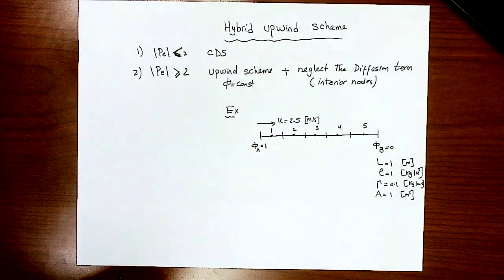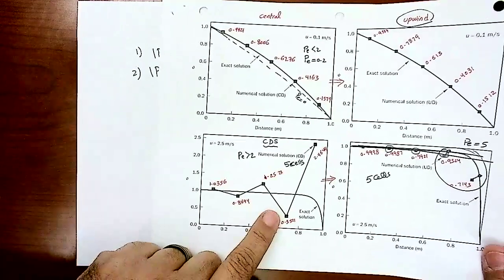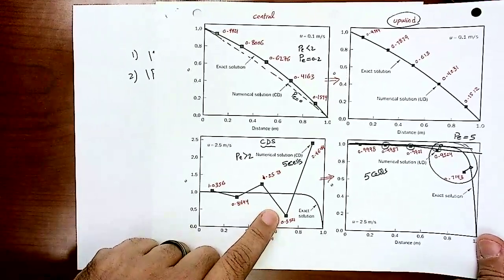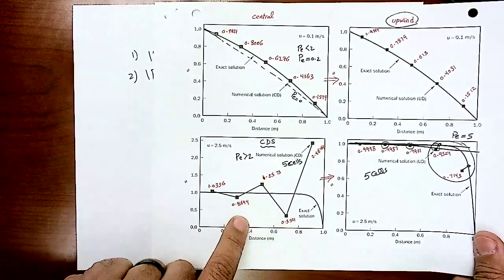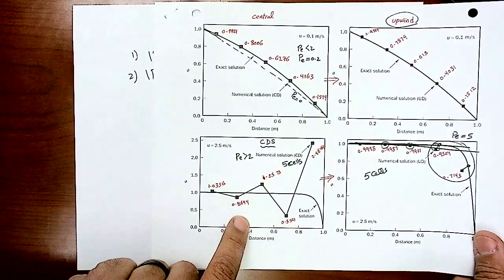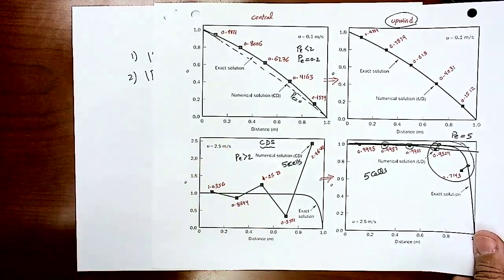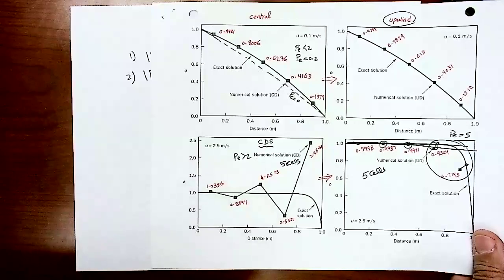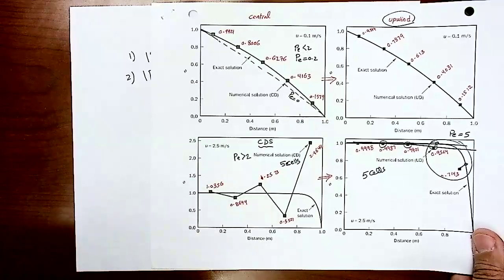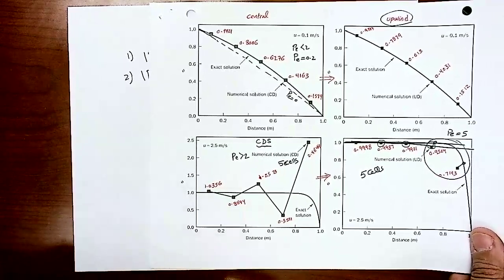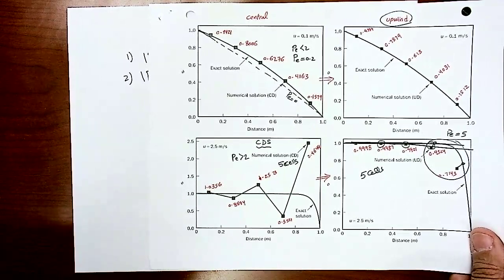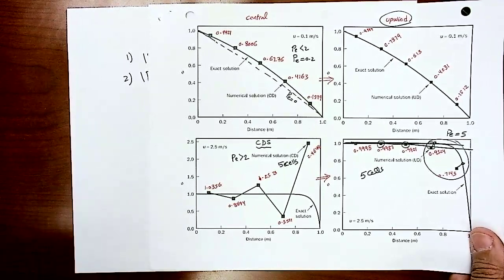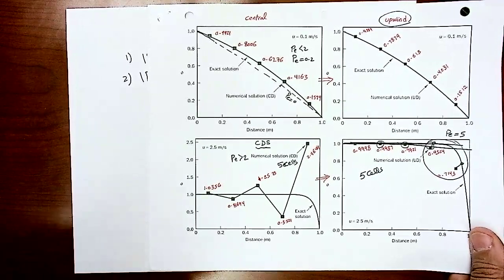We did the first trial using central differencing scheme. We got that divergent solution. That was our first trial. Then we applied the Upwind scheme using 5 cells. For this solution, we went from 5 cells to 20 cells to drop the Peclet number to less than 2, and it works. But it costs you more work. Instead of working with 5 cells, we had to work with 20 cells. The second solution is to stick to the 5 cells, but use the Upwind scheme, which approximates the convection term with a constant value of the function phi inside the cell.